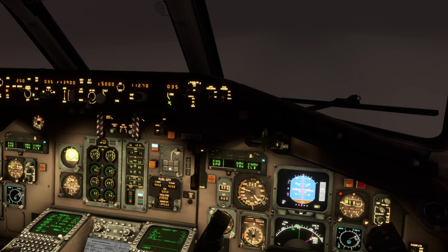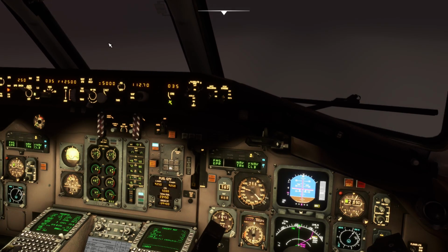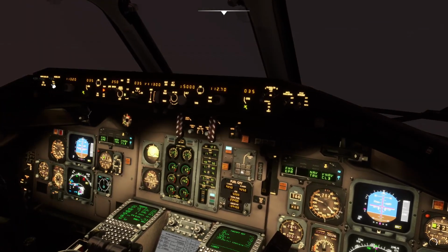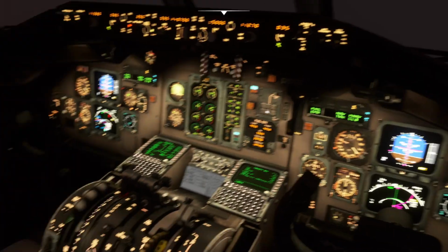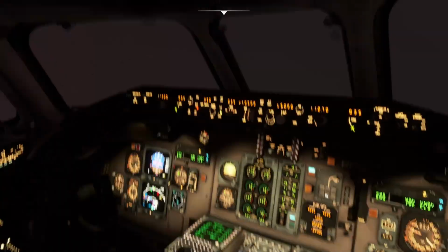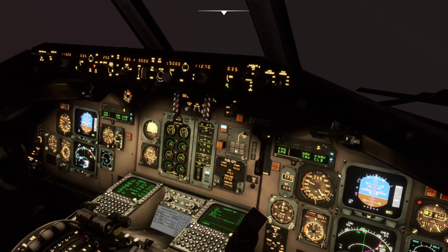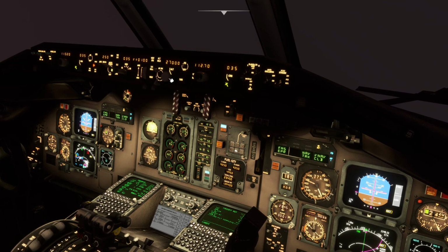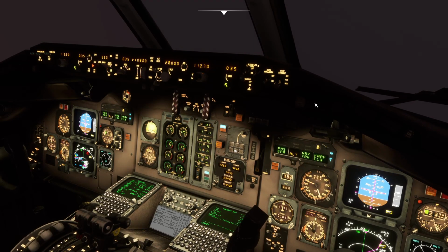Simple as that, yeah? I'm going to put the autopilot in nice and early so I can go through everything else we can do. We can turn off all the lights. I know, kind of interesting. You wouldn't usually be doing that. I'll just check that everything is good here. In that case, we can bug up our cruise level, which is now 280, and just click it to arm it. You'll know it's armed with the little orange alt.